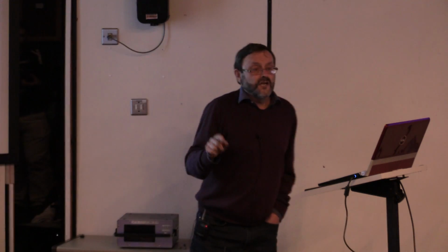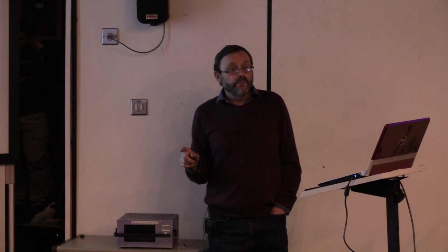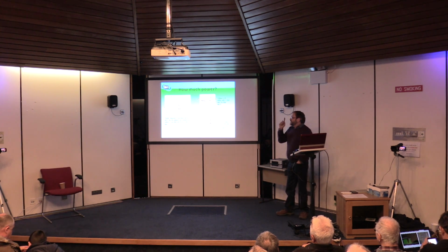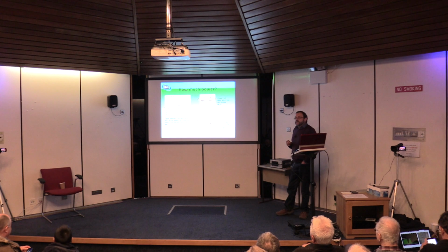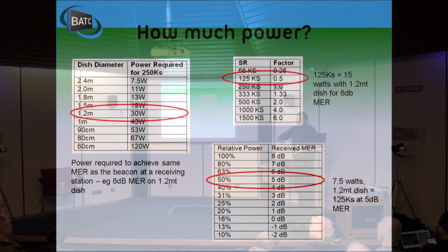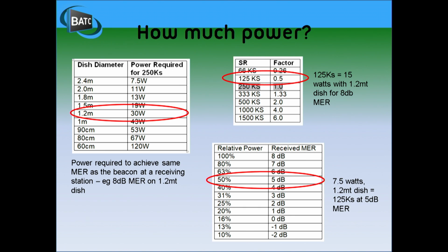And don't forget, the other challenge for us, we can't run 30 watts out of a 30 watt PA because of the linearity of these devices when you're running wideband signals through. The general rule of thumb is back off by 6 dB. And so this is a pretty crucial table. If you try and run more than that, the shoulders or the spectral regrowth just climbs. And it's a real problem on all bands, but on 2.3 it becomes more of a challenge. So they're the typical numbers.